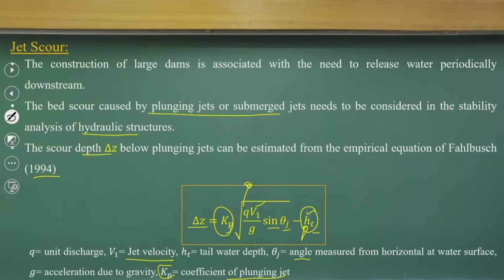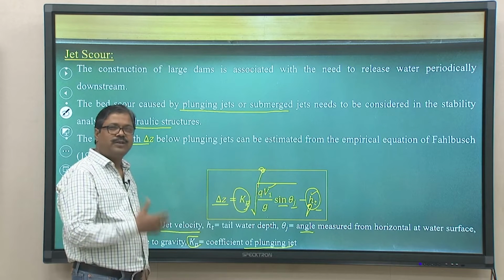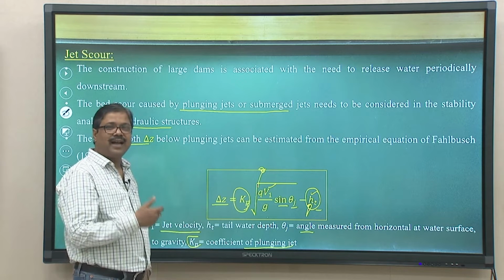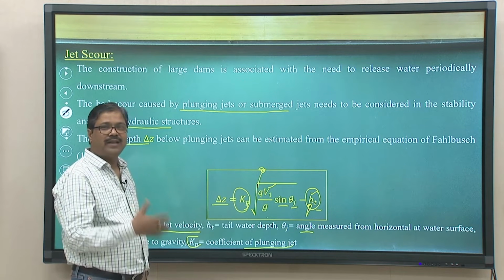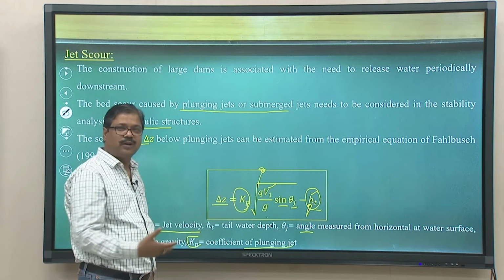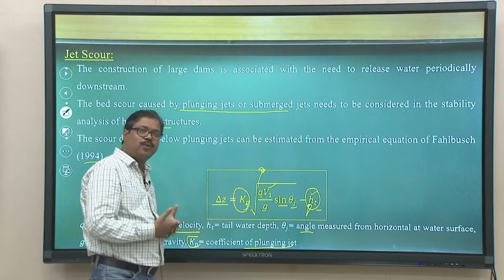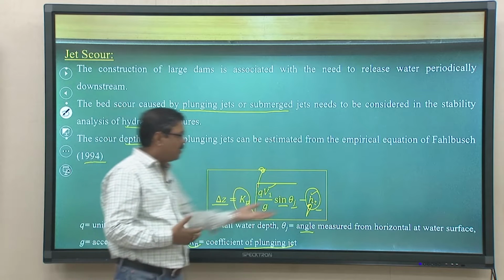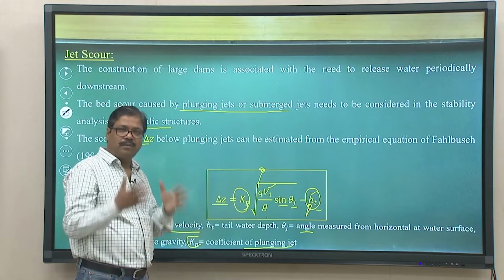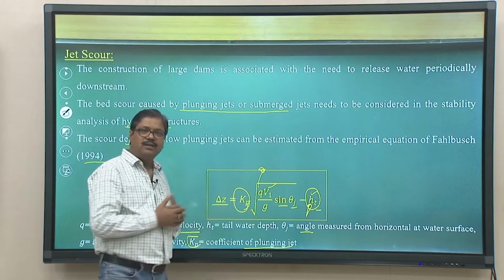So, what I am saying is, if you look at the empirical equations, we always try to understand them, and that understanding gives us a guiding principle for how to manage hydraulic structures during scour formation in extreme flow conditions. That is the biggest idea: if very extreme flow conditions are coming, we need to have the tail end water depth at major bridge, dam or weir locations in such a way that we can reduce the scour depth.